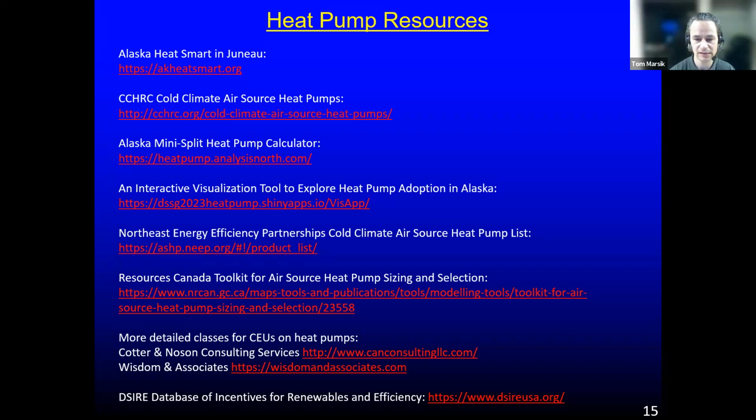So you are burning less oil because you are providing some of the heat from the heat pump, which means you are using more electricity. And that's when it's important to understand this concept of heat pump COP, so we can make sure we will operate the heat pump in the conditions where the savings that you're achieving in the oil are greater than the extra energy and cost that you have because of the extra electricity consumption.